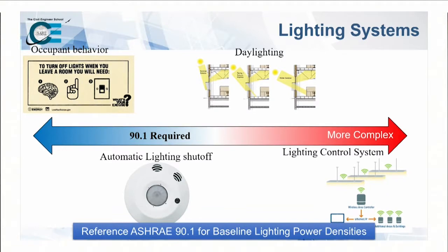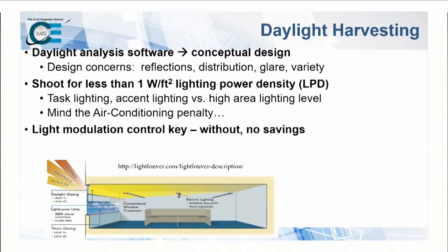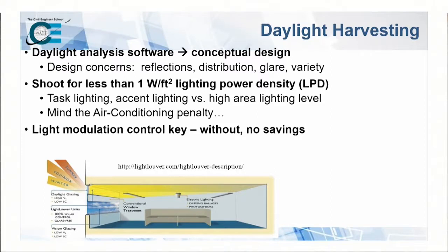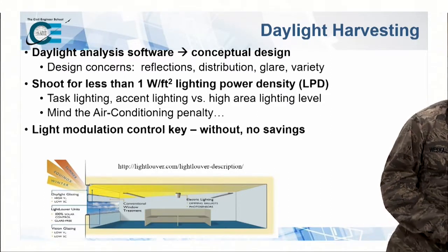And ASHRAE 90.1 has baseline lighting power densities. So as you're going through and figuring this out, you'll have to refer to the baseline power densities in ASHRAE 90.1. So daylight harvesting, this is complicated. We have daylight sensors, and